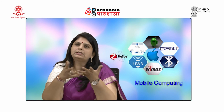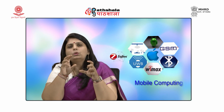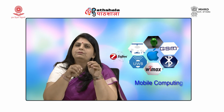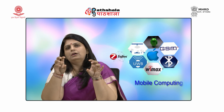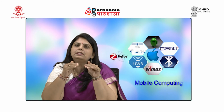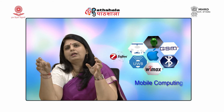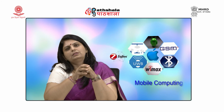Now, the speed of the signal is the same, that is the speed of light. So, there is no change. What will happen is that due to the increased travelling distance, each signal will arrive at the receiver at different times. The signal which covered the smallest distance will reach first, then the signal with lesser time will reach, and then the signal which took the maximum time will reach. So, the signals are arriving at different time intervals, and this effect is known as delay spread.